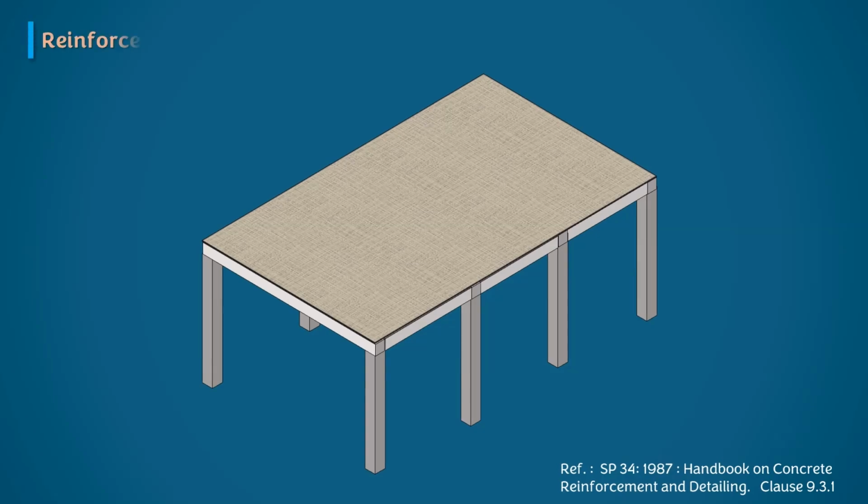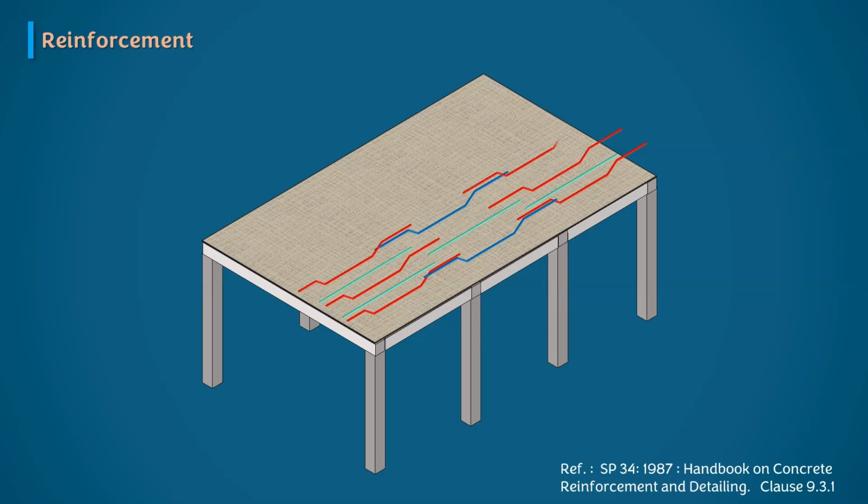The calculated spacings required theoretically in different spans or support regions are not directly provided. In practice, it is desirable to correlate the spacing requirement at the different locations of the continuous slab and to provide either the same spacing or a fraction or a multiple of it in all spans or supports so that placement, including bent up over support, becomes convenient.